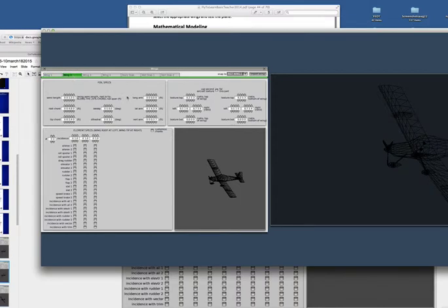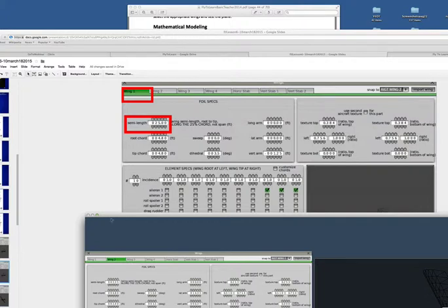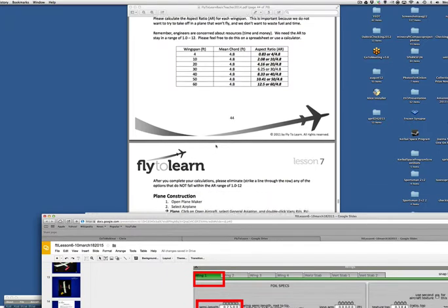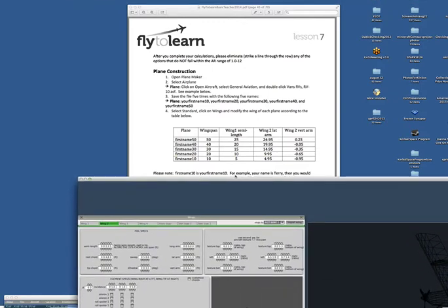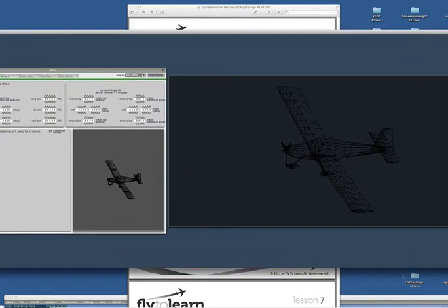Then we're going to go to wing 2. And if you look on your table, we said wing 1 semi-length of 25, wing 2 lateral arm of 24.95, vertical arm of 0.25. Let me show you what we're talking about in this. So if I go to wing 2, now I'm no longer in wing 1, I go to wing 2, I've got to move those wing tips out on this. You can see that the wing tips are right here, but this is now the end of the wing.